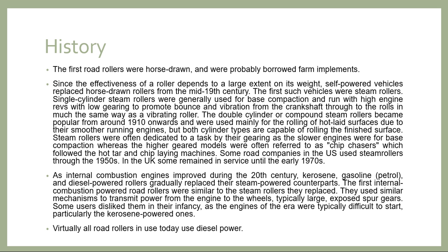Single cylinder steam rollers were designed to run with a high engine revolution with low gearing to promote the bounce and vibration from the crankshaft through to the rolls, much the way a vibration roller does.